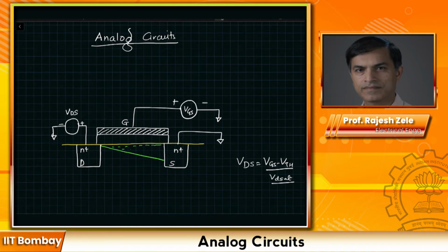So these are all the electrons which have been withdrawn from the source, and exactly where the drain is under the gate, we will say that the channel is pinched off when VDS is equal to VGS minus VTH. And if you remember, this is our channel length L.